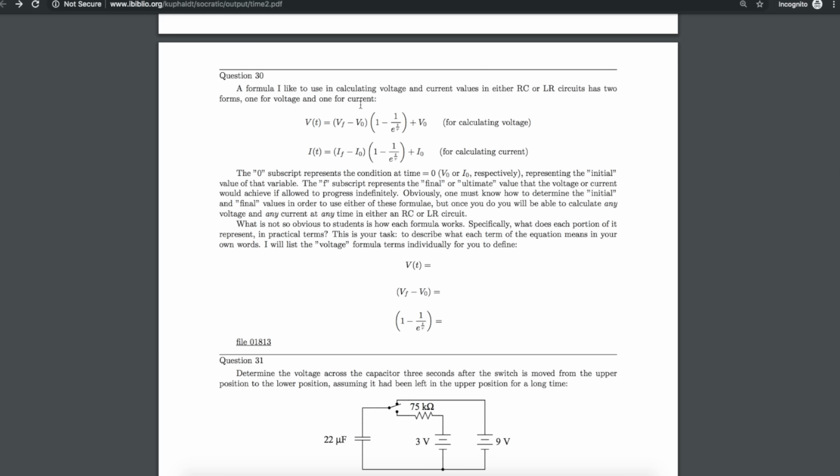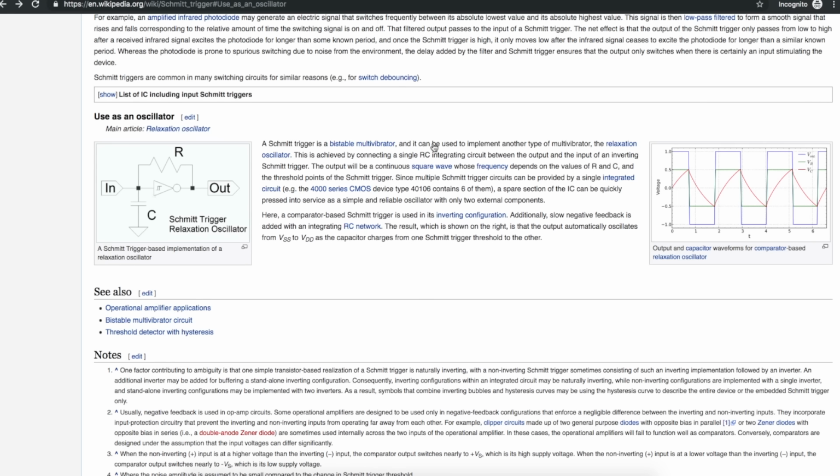So in the end, we know everything here in our case except t, the time. We know the RC values for the RC time constant. We know that our ultimate final voltage, if we let it keep charging or discharging, is either going to be close to 5 volts or close to ground. And we know the target voltage we're looking for and the starting voltage we're going from. Those are the lower and upper threshold voltages of the hysteresis.